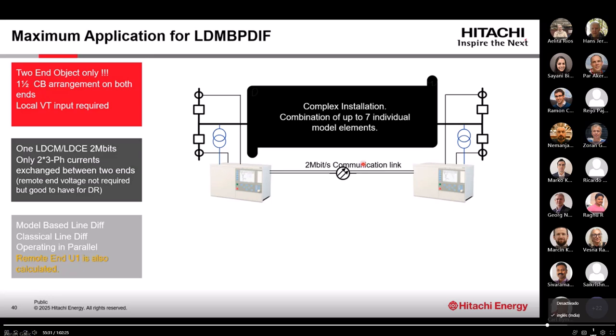However, in a 2 megabit communication link you can transfer 9 signals, so you can transfer the voltages as well. They are good because when we record everything, we can verify the ABCD parameters, or even calculate them. Therefore, remote voltages are not required, but it's good to have them, because if any issue comes, we can quite easily calculate everything. Okay.